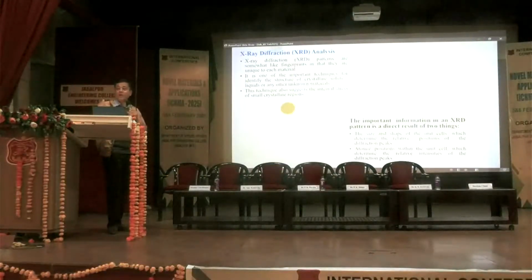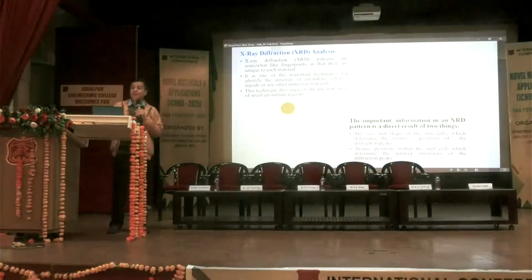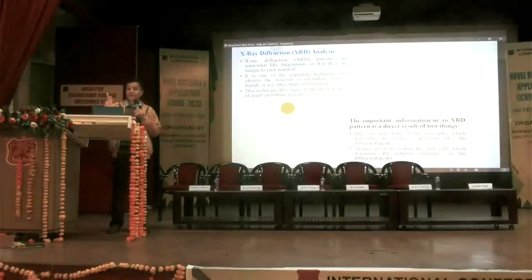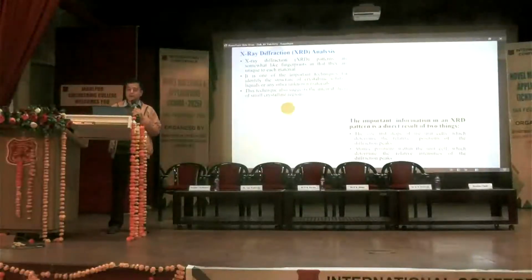And everywhere you are putting your attendance by your thumb or something. Why? Because every individual has an individual identity through their fingerprints. Similarly, here, if you see the materials, every material has a unique property in terms of its crystalline structure, then in terms of its stress or small regions. So you can do this with the XRD analysis. That's why for proper structural analysis, XRD is the fundamental requirement of any study.